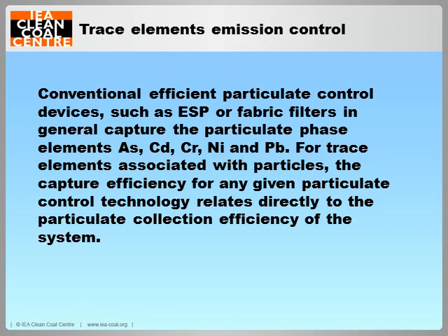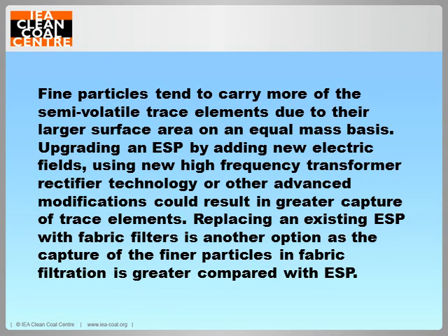For trace elements associated with particles, the capture efficiency for any given particulate control technology should relate directly to the particulate collection efficiency of the system. Fine particles tend to carry more of the semi-volatile trace elements due to their larger surface area on an equal mass basis.